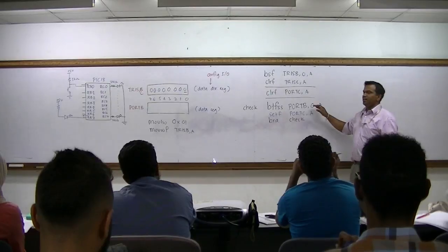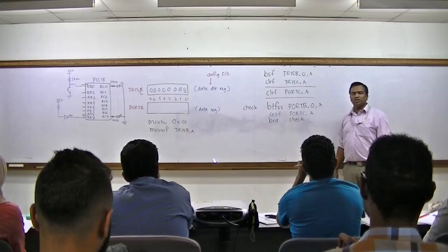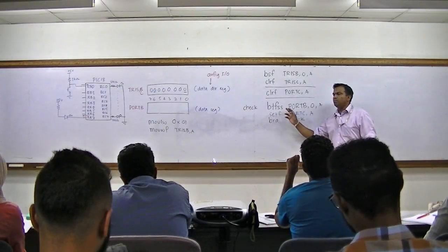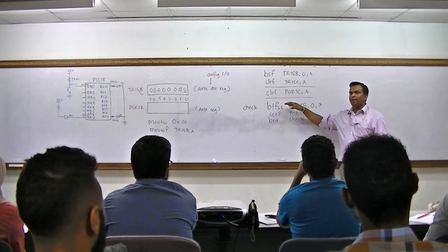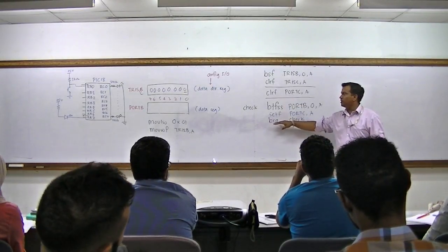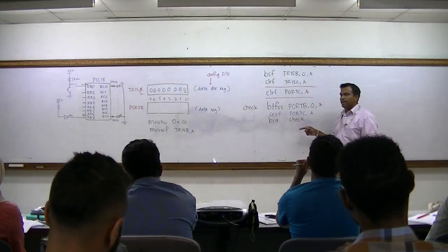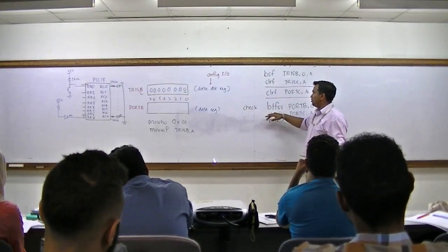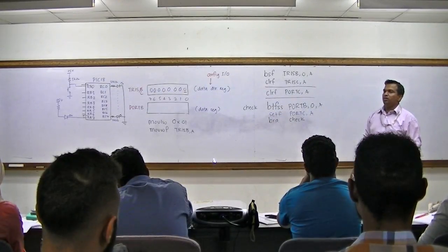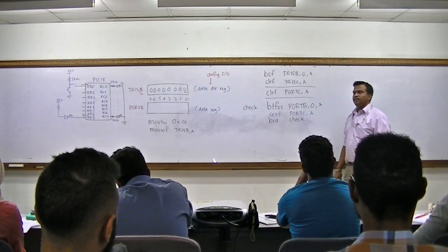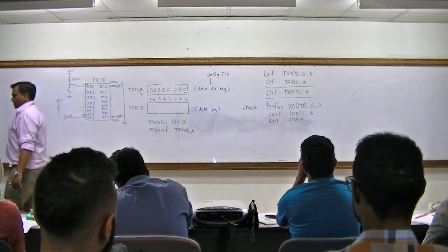And then we need to check whether the switch is being pressed or not. So we use the bit test instruction. Here we are using skip if set, which means if it's not pressed, it will keep skipping. So what you want to do is keep checking whether the switch is being pressed or not. The moment the switch is pressed, what happens? It won't skip, it will go to set F port C, which means all the LEDs will be turned on. You get it? Yes or no?